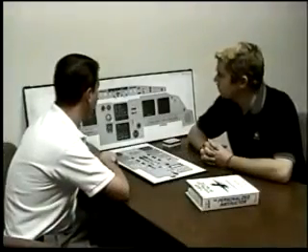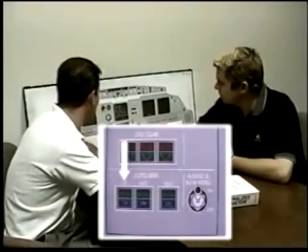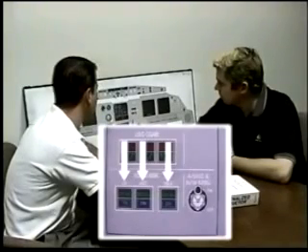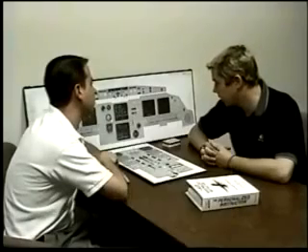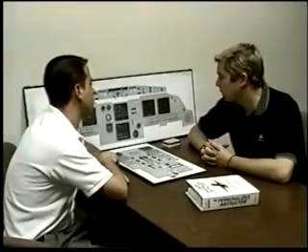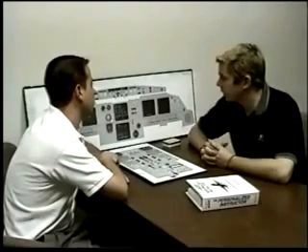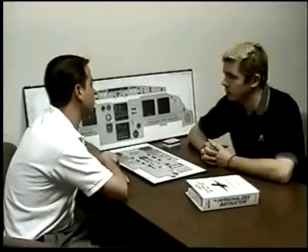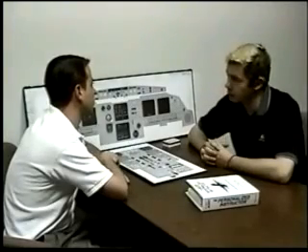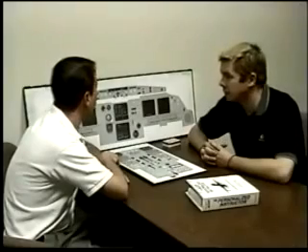Let's talk about brakes. Starting with auto brakes. Walk me through low, medium, max, when you would use these. Okay. Auto brakes are only available in the green system, and I'm going to use low for most of my landings. I'm going to use medium anytime my landing distance is increased, or anytime I'm in low visibility ops like Cat 2, Cat 3 ops. And I'm going to use max during takeoff.